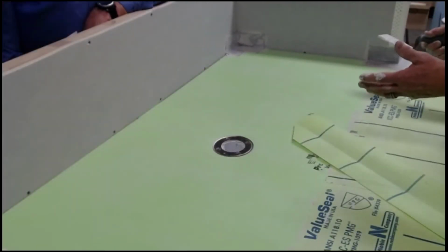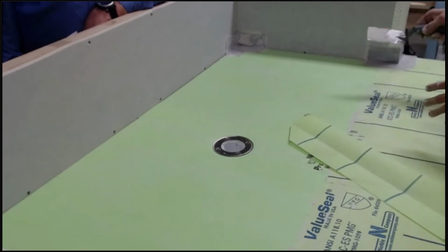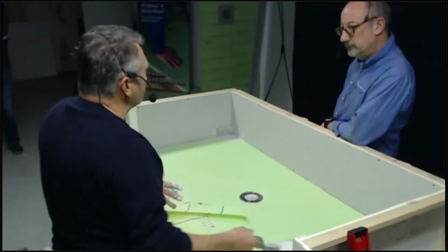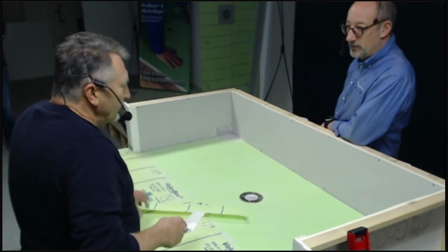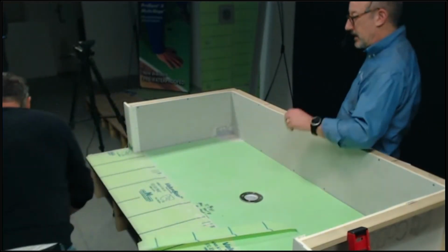All right, then I'm ready to go ahead and use cap strips. There are a couple of different ways to do that. You can use cap strips. You can put your wall membrane on and lap down onto the base. If you're using Aqua Blue, you can transition to the cap strip, or you can bring the Aqua Blue and lap down onto the base too. So you really have a lot of choices on how you want to transition.